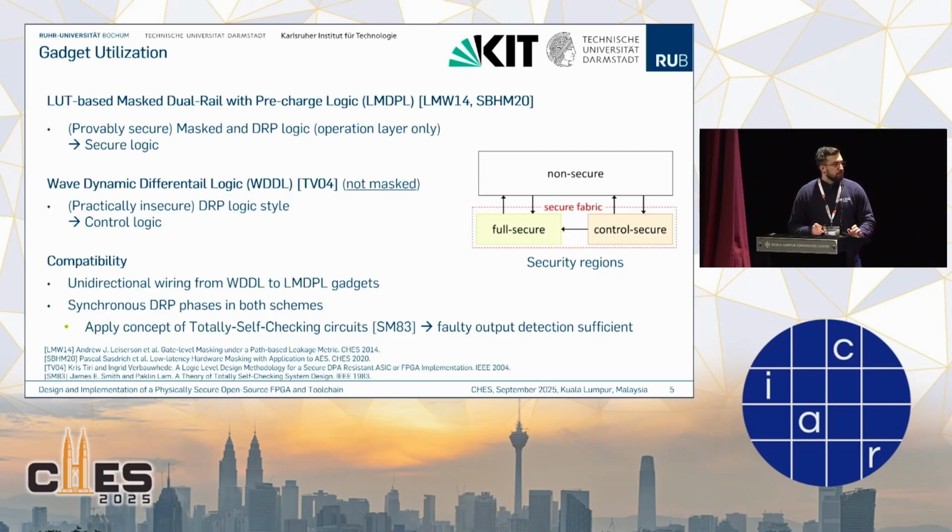What this means is that as soon as in this entire composition, the faulty state 1-1 or faulty state 0-0 is reached, we are not allowed to go back to a valid dual rail state in the succeeding circuit. As soon as one of these states is reached, it is going to be propagated through the composition until the primary outputs, where it is then sufficient to deploy some kind of fault detector which can detect one of these states.